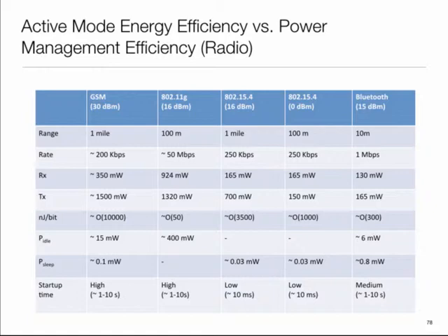It's not instantaneous. Whereas one of the things that the folks in Zigbee did, by that time Bluetooth had been around for a while, right? Zigbee came into being a few years later, and by that time the consciousness had set in. So they explicitly went around doing a few things. One of which was they wanted to make sure that idle power was less, which is, sleep mode power was less. So you can see that 0.03 milliwatt versus 0.8 milliwatt.